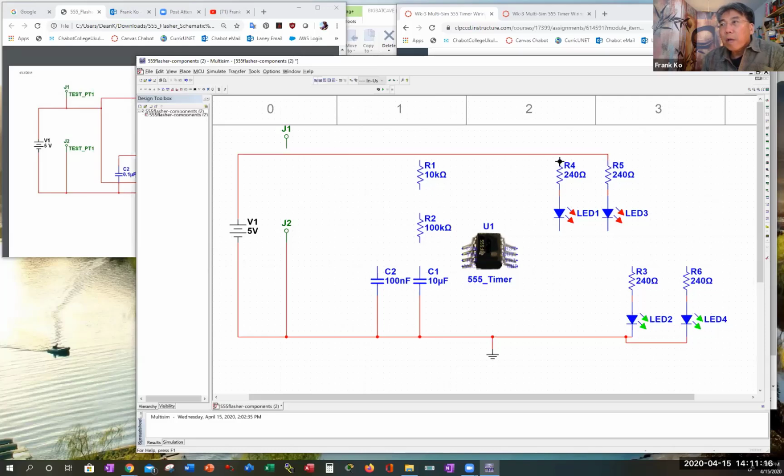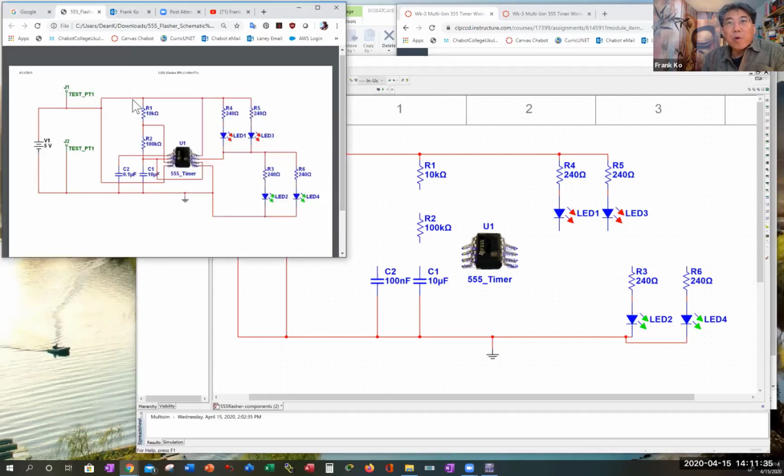there, and bring this and connect there, and bring this and connect there, and bring the jumper wire number 1 and connect there. So the top of the voltage source connects to J1, R1, R4, and R5. Do we have the top connected to J1, R1, R4, and R5? So far, so good. There's another wire coming down from here to the first pin of U1.